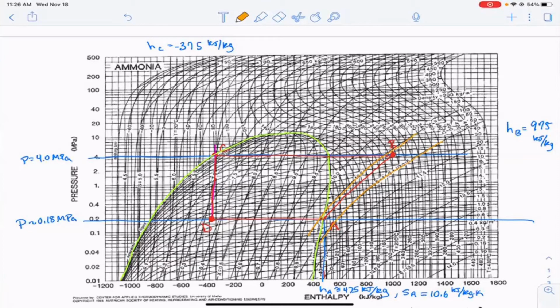Are you talking about, I don't know if I understood your question correctly, but are you talking about here? No, up at the top of the saturation curve. So like on the other ones, we always kind of split it in half and said liquids on this side. Oh, no, that's also true. Okay. So that's still the critical temperature and pressure at the very peak here. And everything to the right here is saturated vapor, and everything to the left there is saturated liquid. Yeah, good question. Sorry, I misunderstood. Yeah, good question. All right, anybody else?